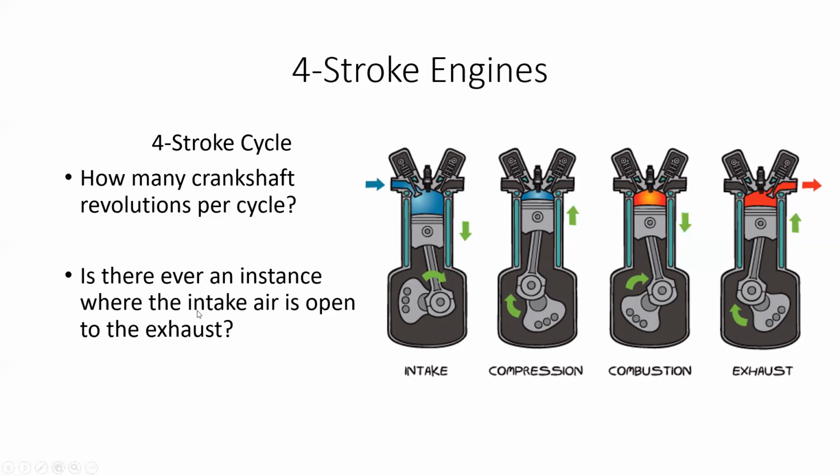Is there ever an instance where the intake air is open to the exhaust? In a four-stroke engine, in a stock application, no, there really isn't much time when the intake is open to the exhaust. We're going to talk about why that's important when we talk about two-stroke engines. But there's never an instance where raw fuel is open to the exhaust.